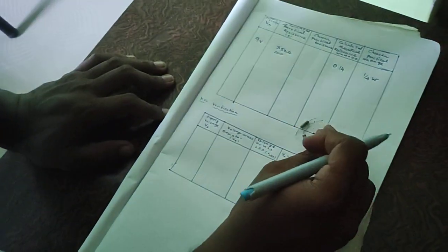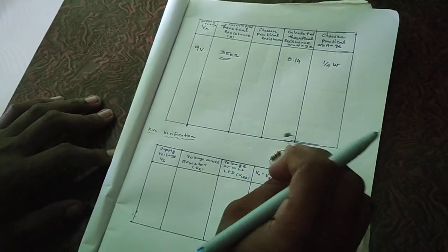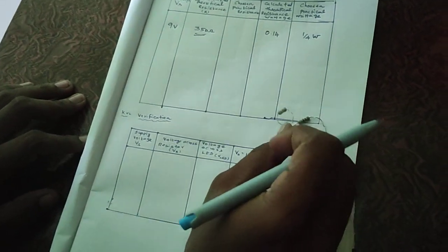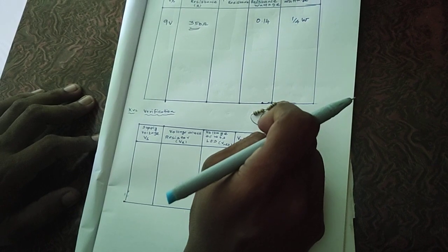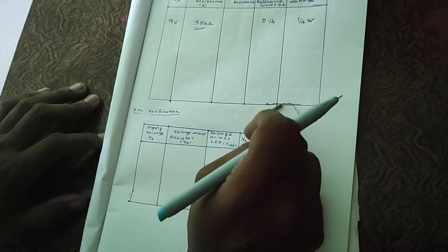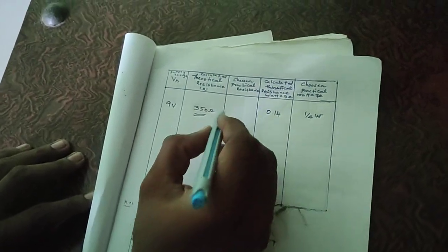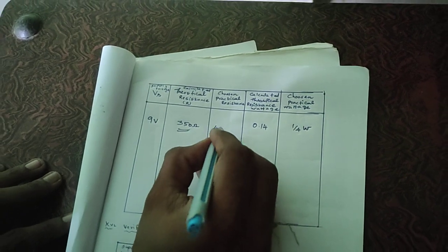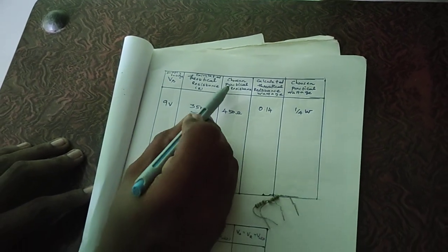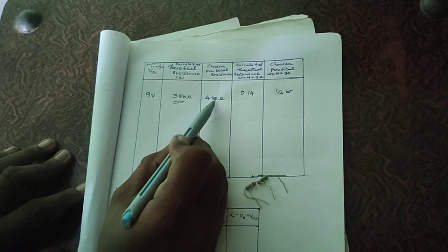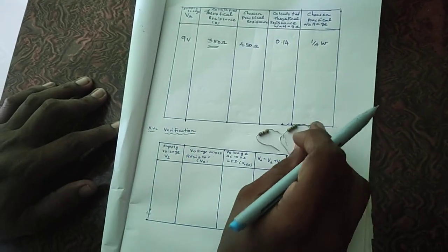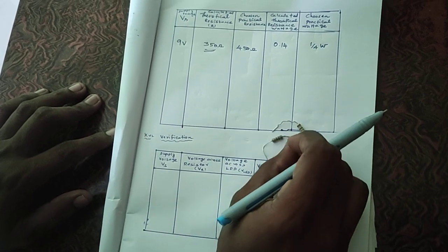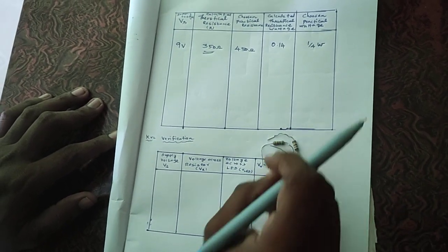Instead of that, I have one resistor of 200 ohm, and one more resistor of 250 ohm. Okay, so I'm going to use both. I'm going to connect both in series to form the resistance, right. So the practical resistance I am choosing is 450. So always ensure that you are choosing a practical resistance which is more than the theoretical resistance. So as I said already, I have resistances of 200 and 250, and both I'm going to use in my circuit.